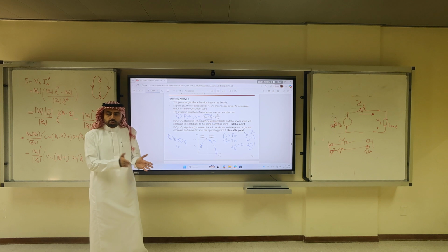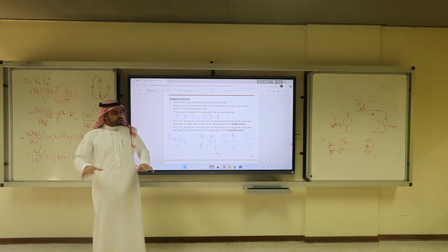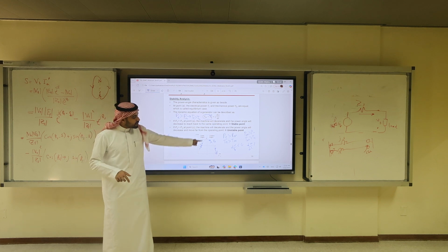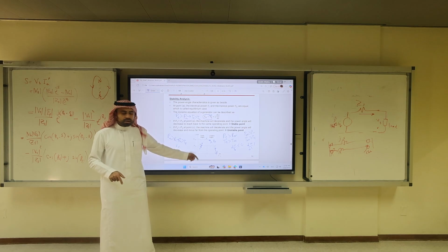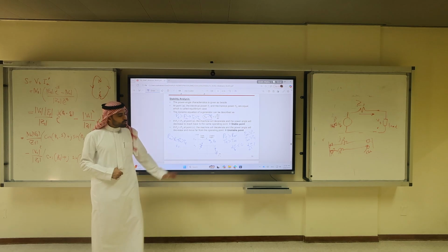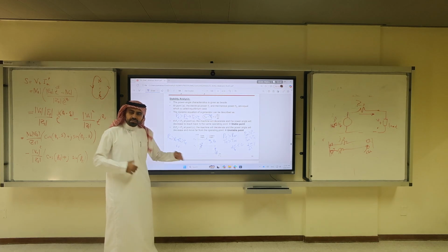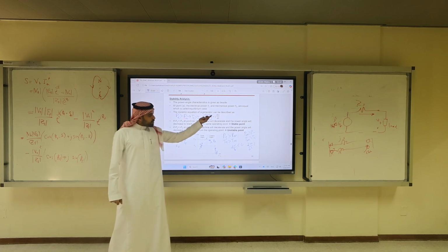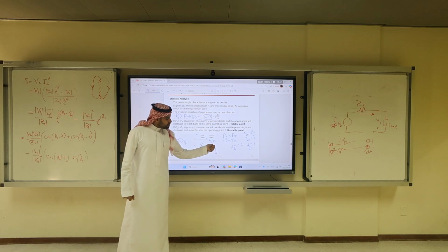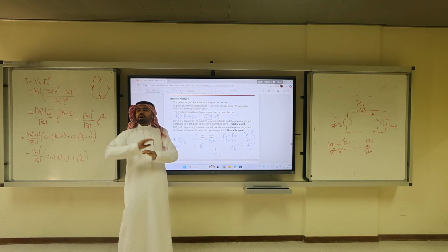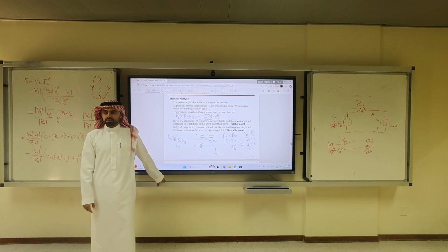Who controls this? There is a control mechanism that links these two together in the stable region. That's why you cannot operate in the unstable region, because the control mechanism governed by the swing equation would accelerate toward not the stable point.